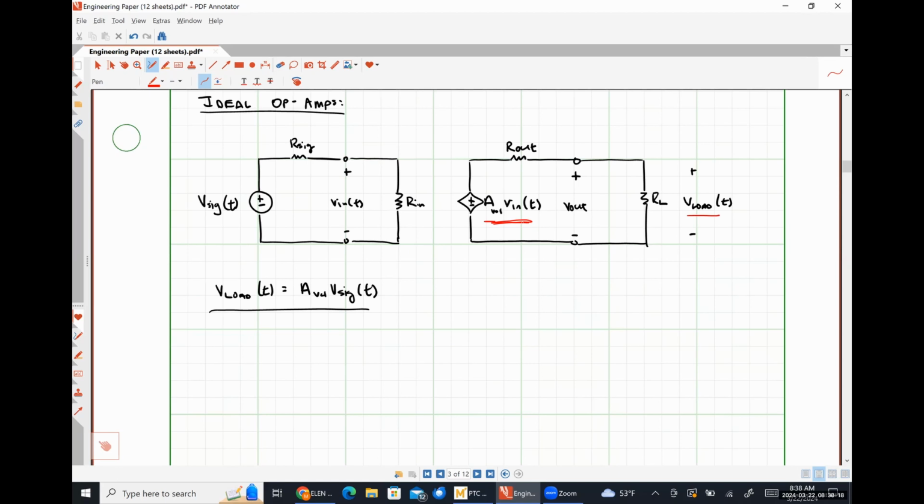Or zero, yeah. So we would need R out to equal 0 ohms for ideal behavior, okay? I agree with that wholeheartedly. So now we need to suss out what it's going to take to make V sig and Vn the exact same voltage. Or what value must Rn have to force that to be true?